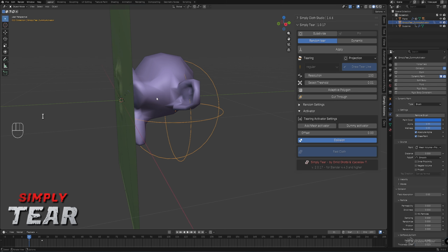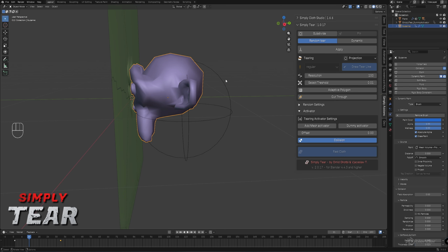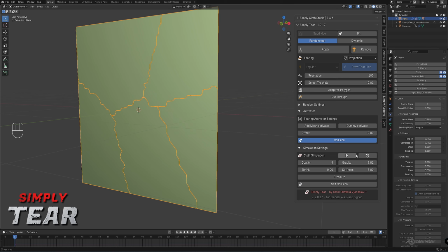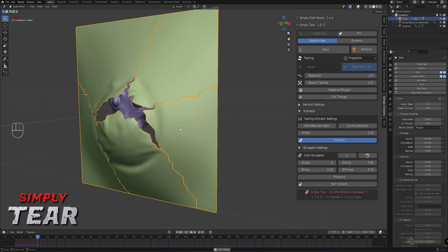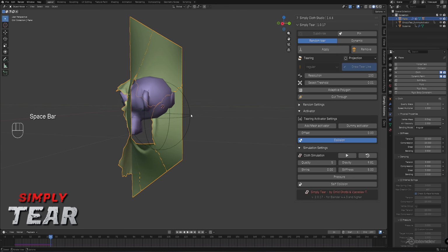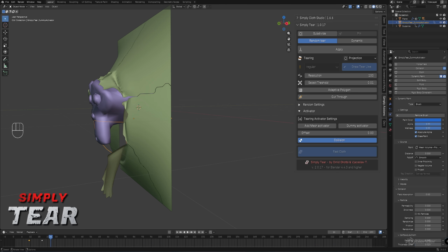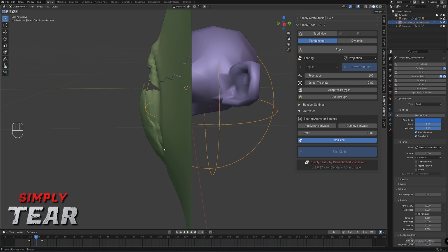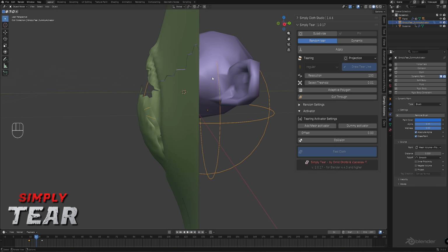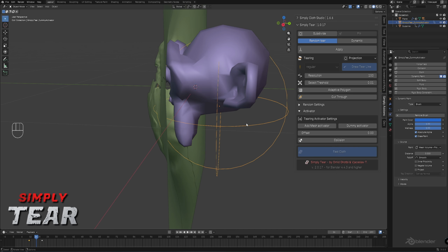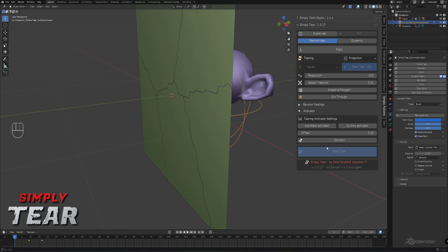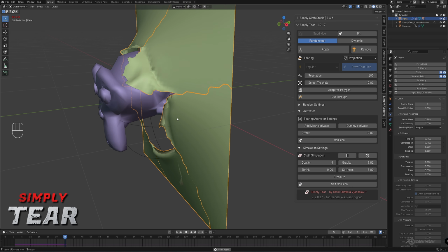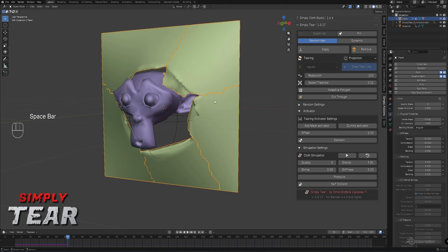So we have here a combination of a mesh activator and a dummy activator. Let's see how the result looks. I select the cloth and you see it works, but I don't want to have collision on it. It destroys the effect. You see it is showing this collision. We don't want it. So this should be the collider, and this should only activate the tearing. And again. Yeah, that's what we want. And it was really fast.